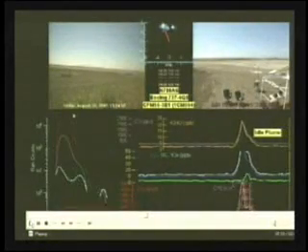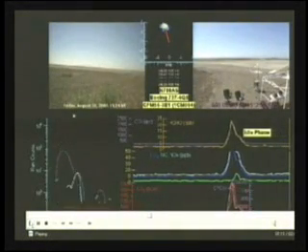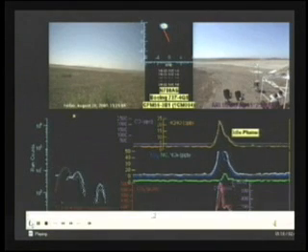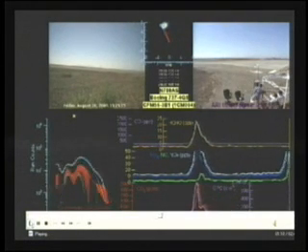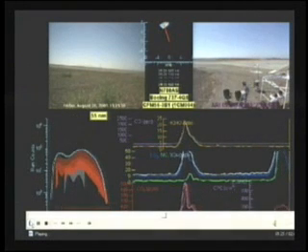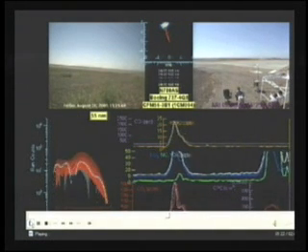okay, that's coming. That's going to take a few seconds to get to us. This isn't quite real time. It's speeded up a little bit. Take a note of what the NOx and the hydrocarbon emissions do. The NOx are now on the same scale. The CO2 is lower, but even with the higher dilution, the NOx are much higher.